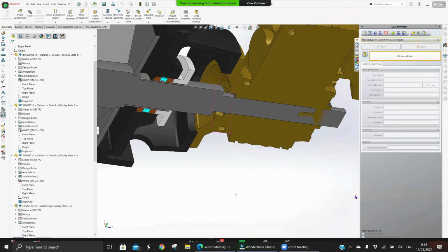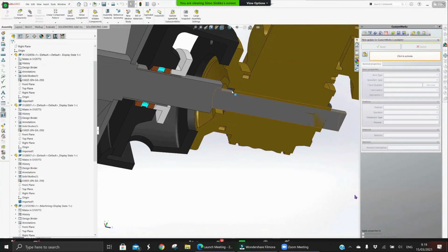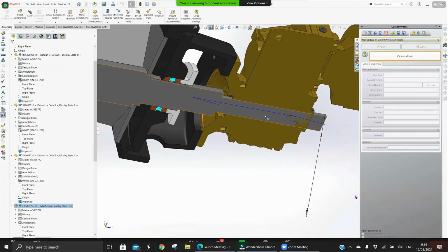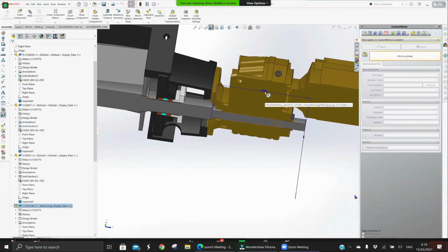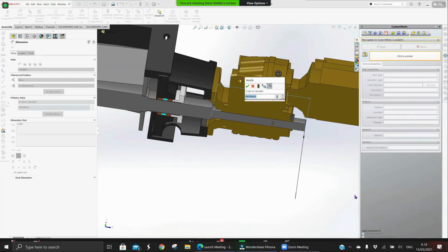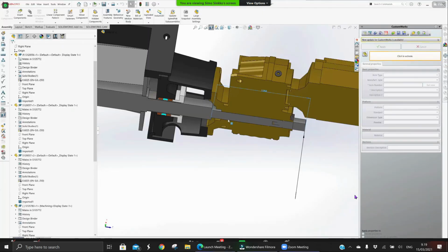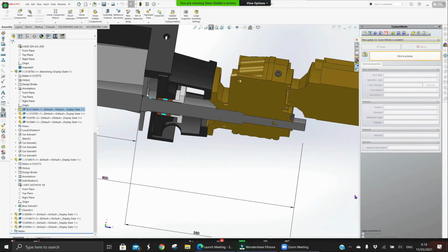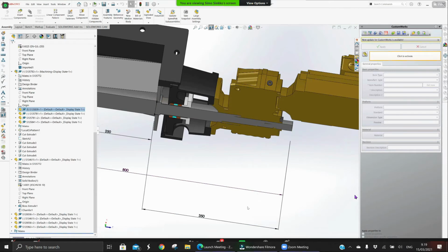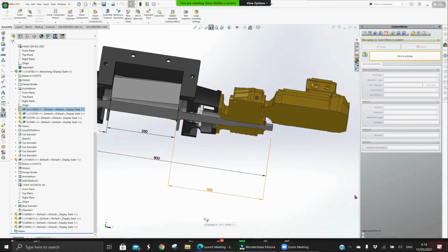So we figured out that the correct diameter is 35 and the correct length here, instead of this 200, should be this 132 based on the information that was given. But I see that if I do it in that way, the shaft in general is way too big, so I need to modify the main dimension that I gave to the shaft in the very beginning.